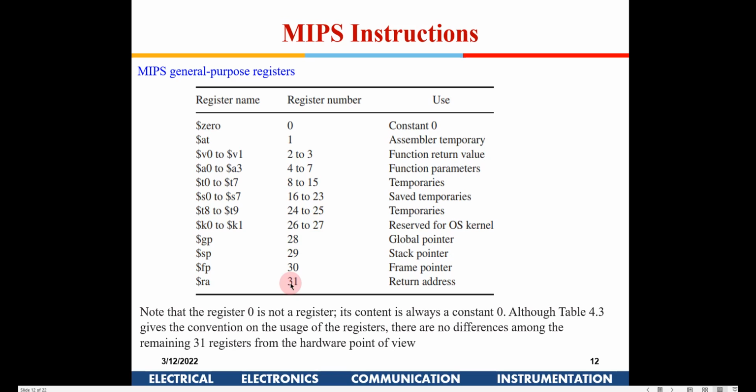So once you are jumping, before the jumping, you are moving away from the main program to do some other program, and then you are coming back, right? Before the jumping, the present address will be stored in register number 31. It's not the present address, what has been executed, but what next needs to be executed. So you are interrupting a program using a jump statement. After completing the present instruction, it will do a jump.